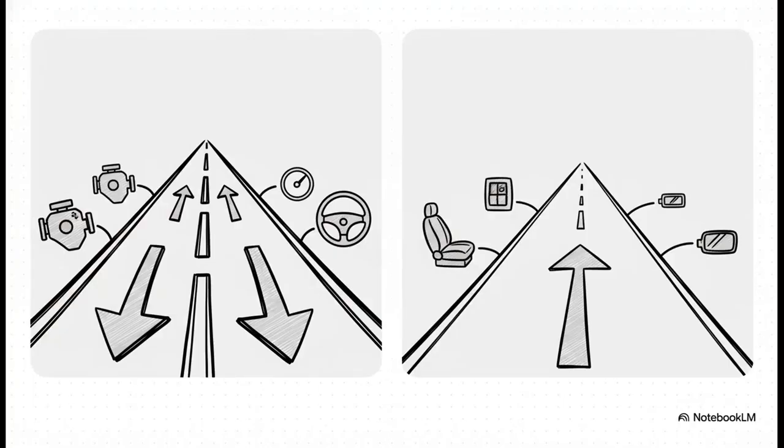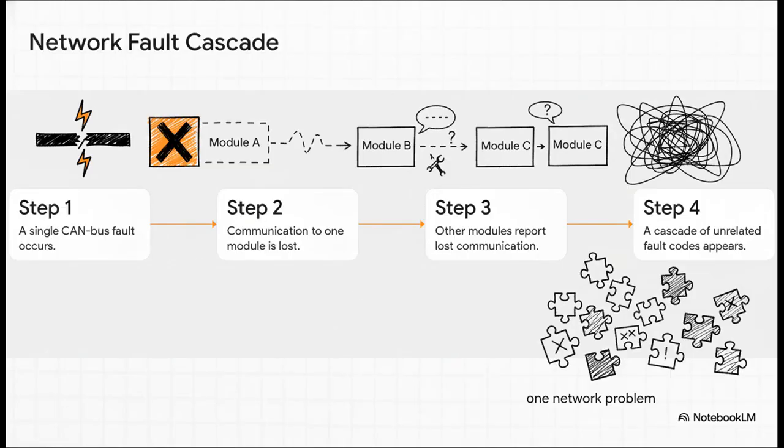On one hand, you've got the CAN bus. Think of this as the main data highway of the car. It's high speed, uses 2 wires to make sure the messages get through clearly, and it connects all the really important modules, the brains of the operation. On the other hand, you have the LIN bus. This is more like a quiet little side street. It's slower, uses a single wire, and it's perfect for connecting simpler things like a window switch talking to its motor.